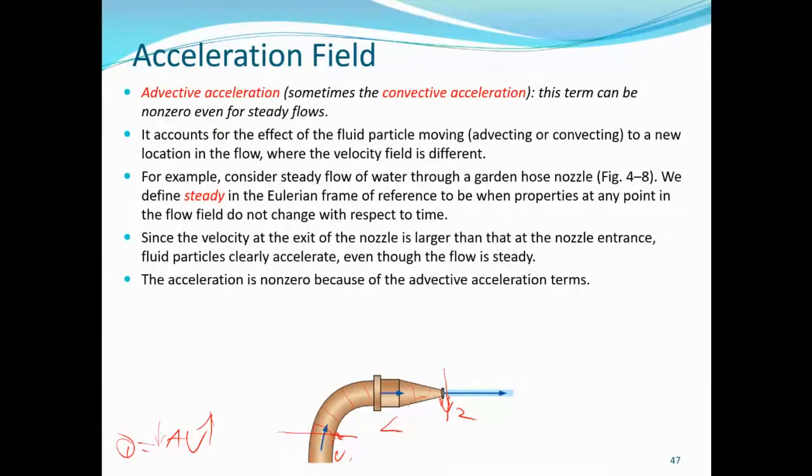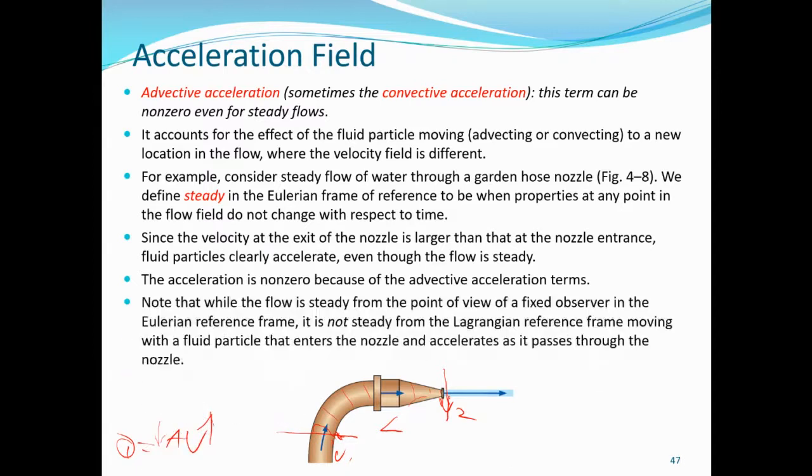The steady acceleration term, which is the local acceleration, del V del T, will be zero because it is steady flow. But the advective acceleration terms will not be zero. And this we will demonstrate in the example that we are going to show later.